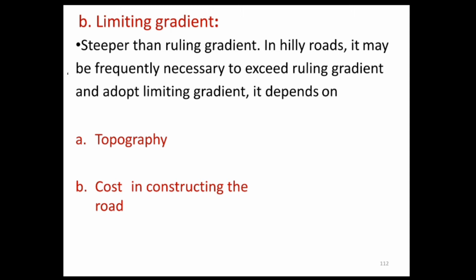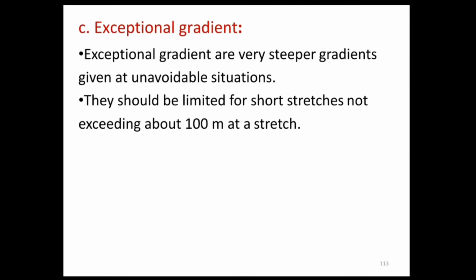In some extraordinary situations, it may be unavoidable to provide still steeper gradients, at least for shorter stretches, and in such cases, a steeper gradient up to the exceptional gradient may be provided. In the case of the exceptional gradient, it should be strictly limited only to a shorter stretch, not exceeding about 100 meters at a stretch.